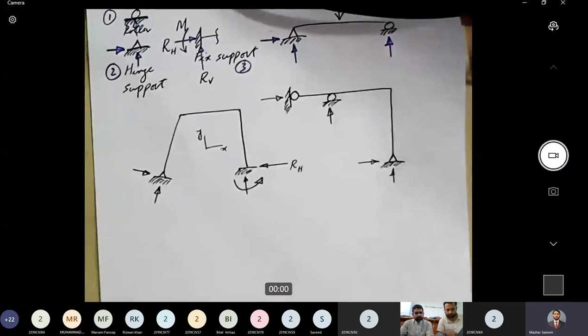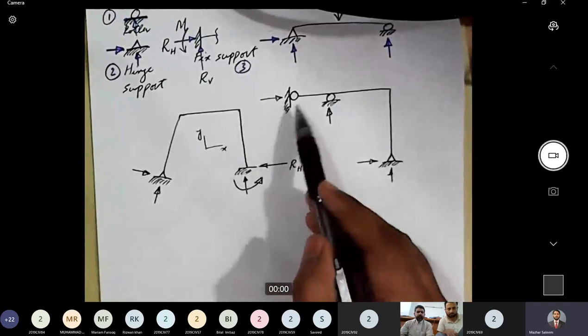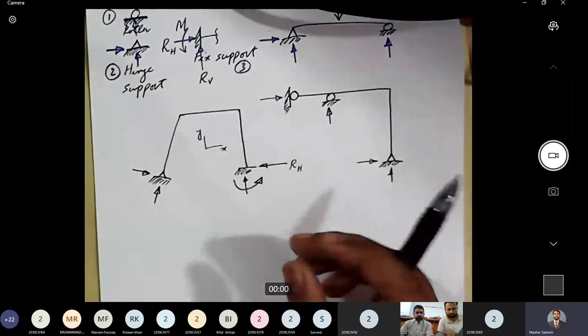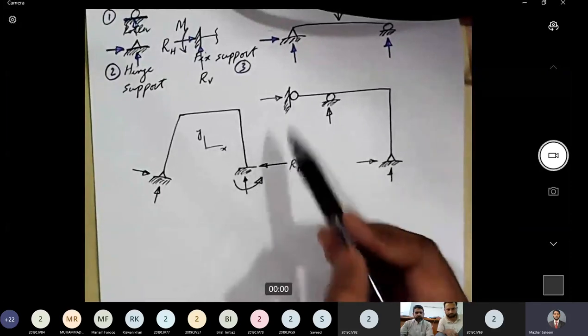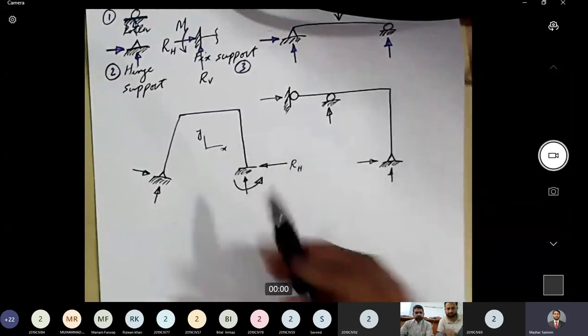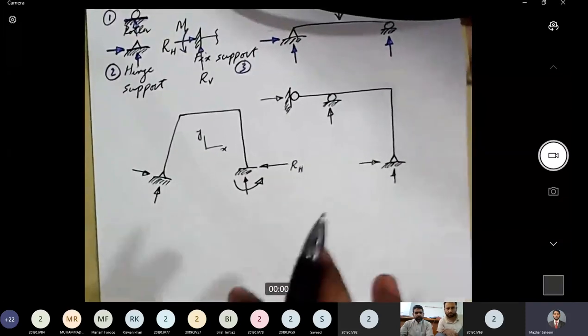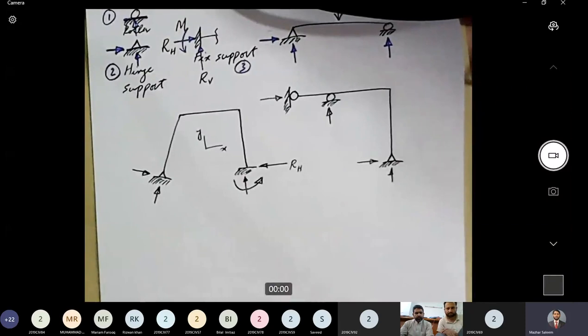It is hard to find a perfectly fixed support that can resist the entire movement, or a support that is truly roller. In only some cases are the supports very close to roller; otherwise they have the ability to generate some reaction parallel to the supporting surface as well because of the self weight of the structure. So as a beginner, in theory we say the actual support conditions are very well defined, but in reality these systems are a bit more complicated.